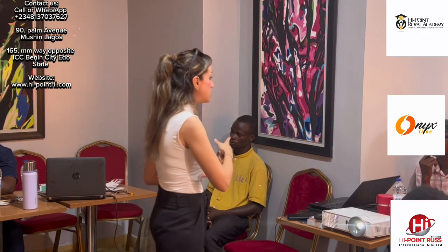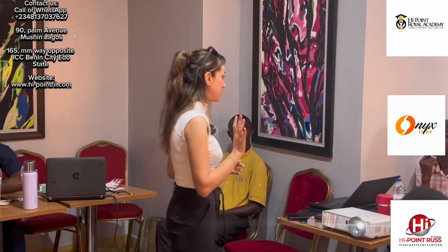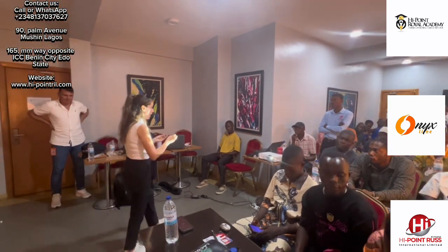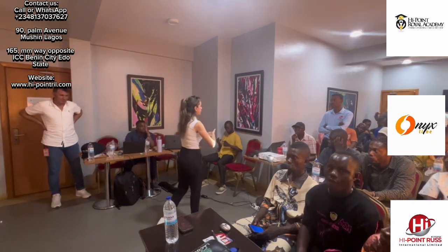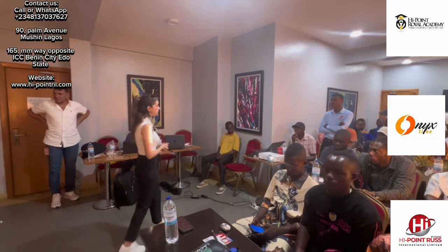You can reach 5%, but use the BMS communication. If you reach 5% and you didn't connect the BMS, the battery will drain and it will block until we do a refresh again for the battery to wake it up.